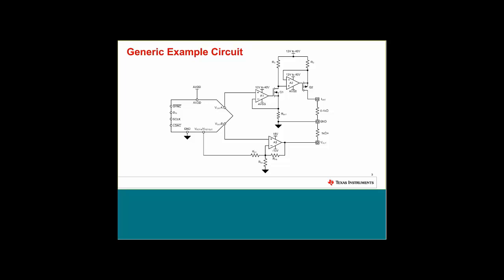In addition, we typically see this kind of 12 to 36 volt high side supply voltage in this particular case. I mentioned 12 to 40 volts because that's what ended up being realized by this design. So we actually have 4 volts of headroom on the high side. And we'll get a little bit more into the implications of this particular structure for a high side current source. But it's quite typical for current outputs in these systems to be in a high side configuration.